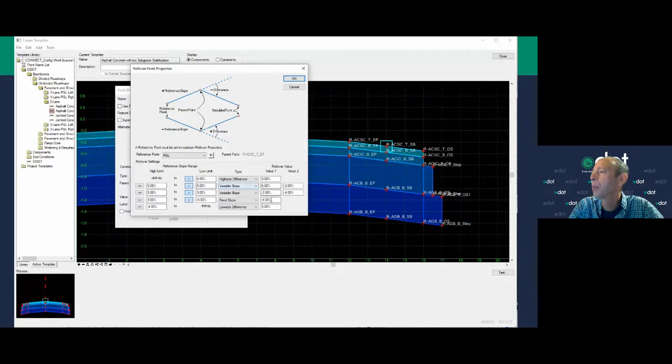So it's these 3 sections in the middle that define those transitions for our breakover and maintaining our 7% maximum break. Looking at the next one down from the top, if I'm less than or equal to 6 or greater than 5, the slope is going to vary through that range, and we have it set at 6% to -2. So at 6%, it's going to be 6%, and at 5%, it's going to be -2, and that 5% -2 is our 7%. So it's really the 6% where it's not maintaining the 7% break.